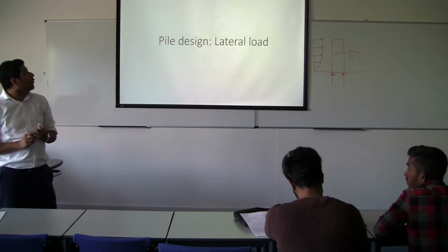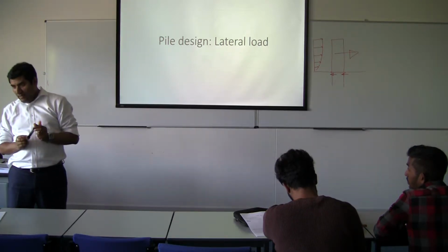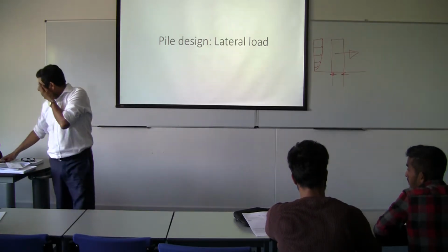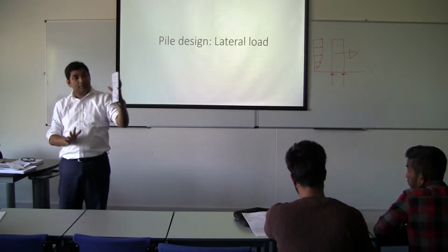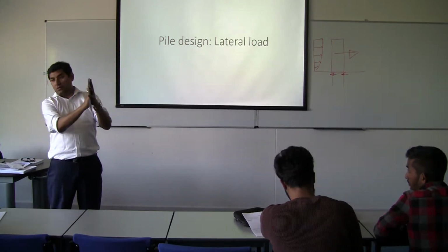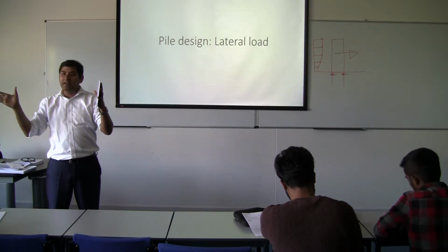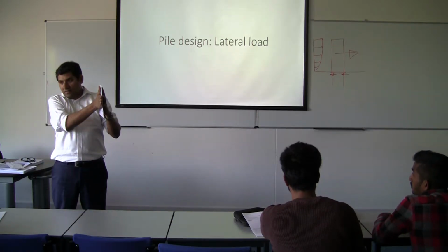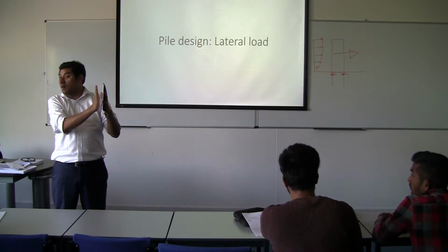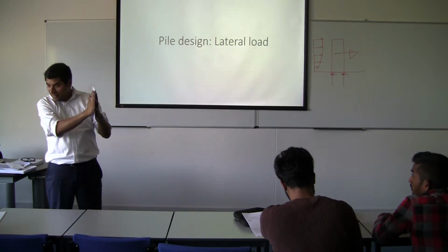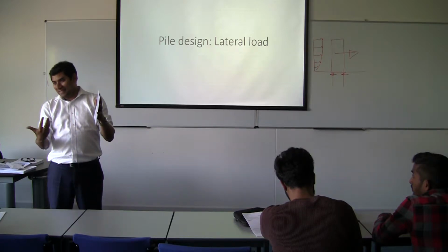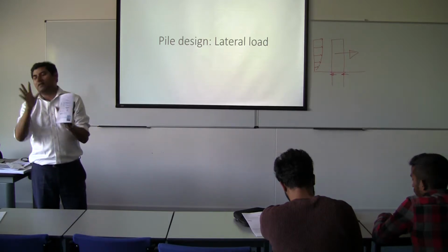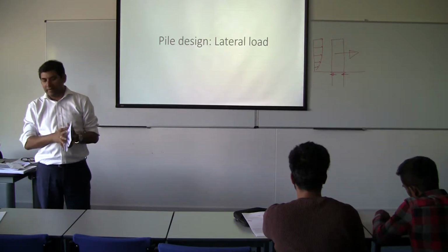Right. From wind speed, you can work out the pressure. It is, because what happens? Basically, if you think about a flow, there is momentum, mass and velocity. Some of the wind is going at say 10 meters per second, and as the wind pushes it, it stops, so the momentum becomes zero. The change of momentum is force, so you can get back the thrust. Roughly 0.6 v squared. It's a thumb rule, but of course there are codes of practice where you can get it exactly.